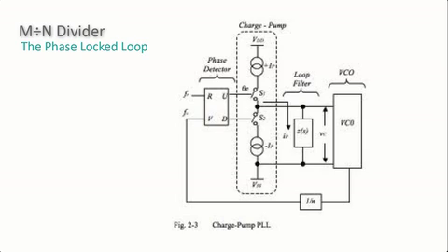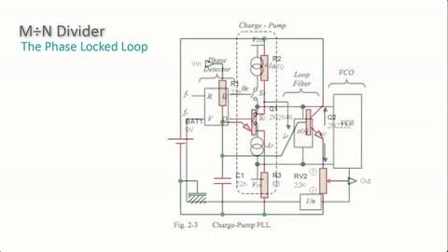Now, in this design, the output of the phase detector isn't swinging from VDD to ground and back. It's just adding or removing charge from the loop filter capacitor, so the signal to the VCO requires much less aggressive filtering. Now, these are just two examples of how to detect phase in a PLL circuit, and there are many others. If you're interested, there are lots of online resources that document many more phase detector designs. But for now, let's turn our attention to the VCO.